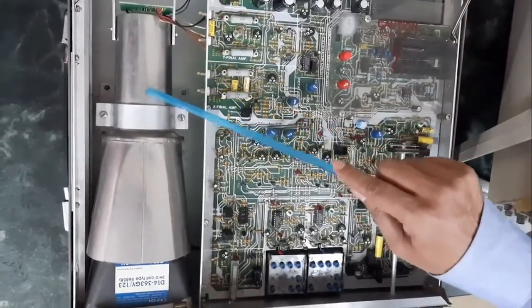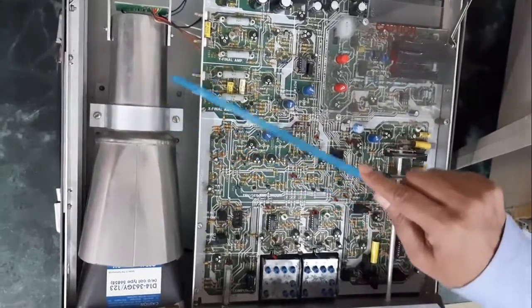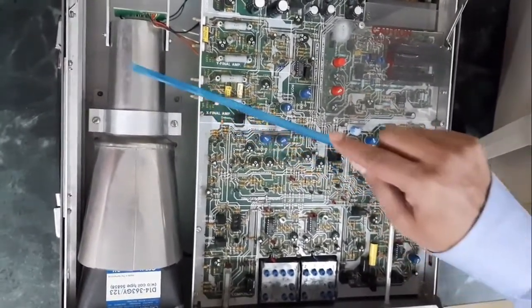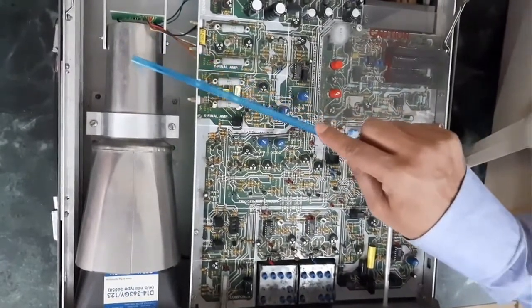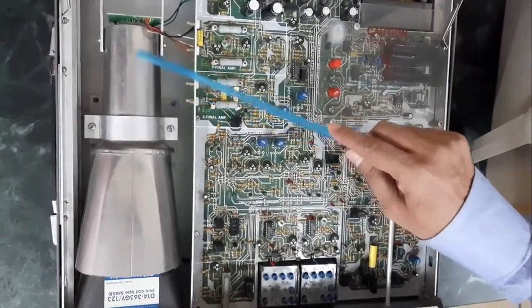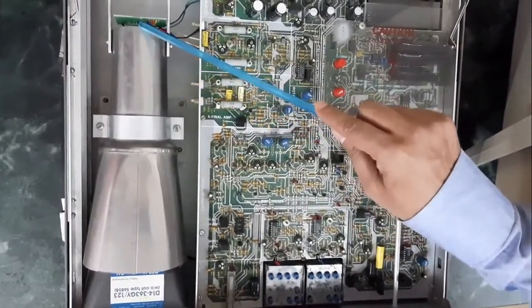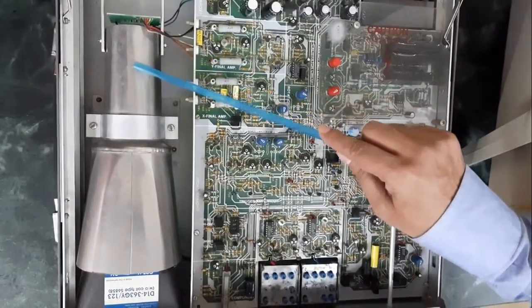But before going to the vertical side of the plates and the horizontal side of the plate, we must have the controlling of the electron, and that's why we have the pre-accelerating anode as well as the focusing anode as well as the accelerating anodes available, and that is covered only by this portion, meaning only 2 to 3 inch section of the CRT only.